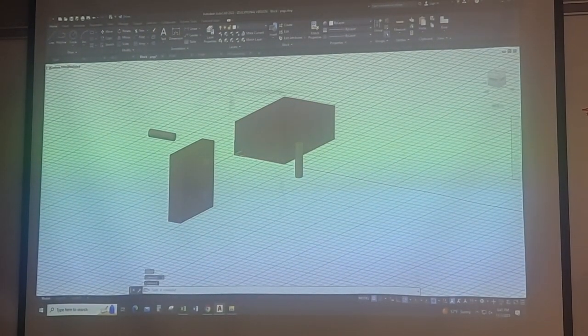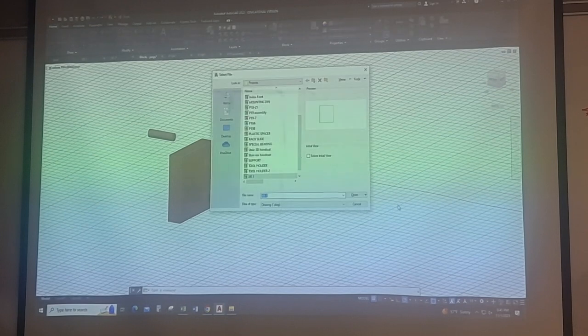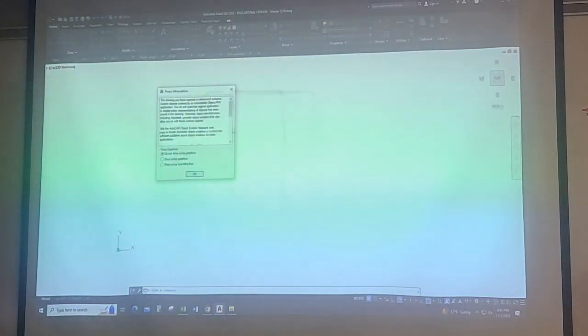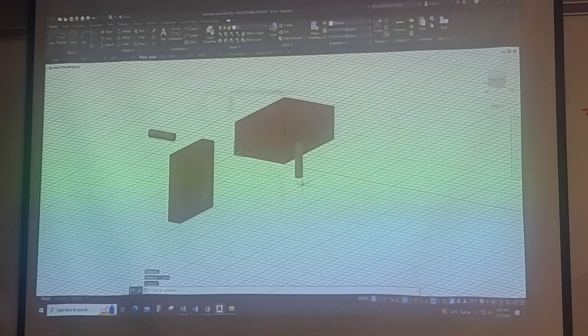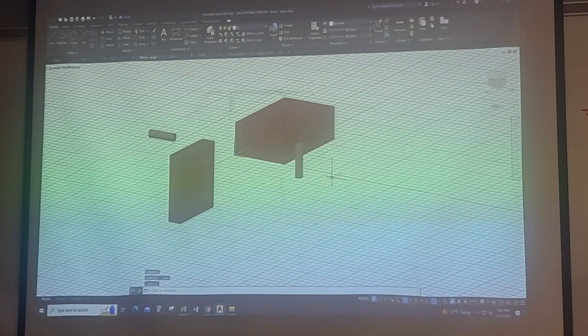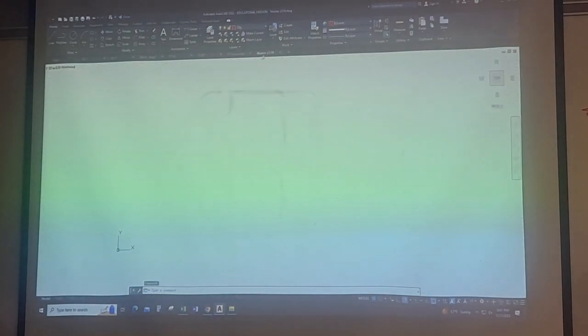So what we've got here are 4 individual objects. What I'm gonna do is show you how to make some blocks. We already know one way of making a block. Let me go ahead and open up my master drawing for this class. So I'm gonna go back to my pegs. We already know how to do this. Control-Shift-C, pick a base point, select an object, hit enter, go to your drawing where you want to put it at.